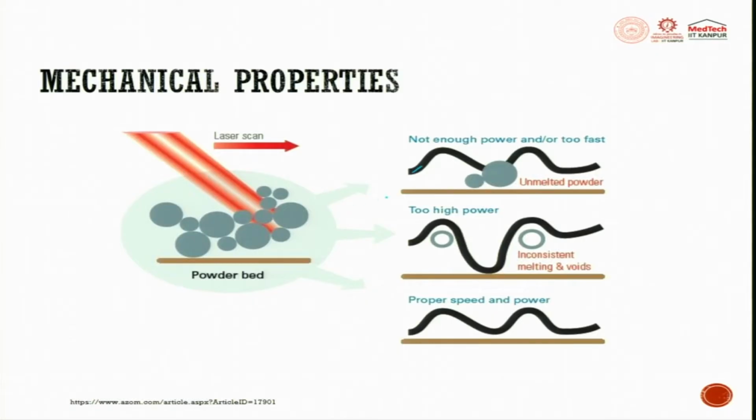If the feed rates are very slow, you will have overlaps like this. When the feed rates are very slow, it is moving in this direction and these are nothing but laser spot overlap. When the laser feed rates are high, you can see how the spots will be created.